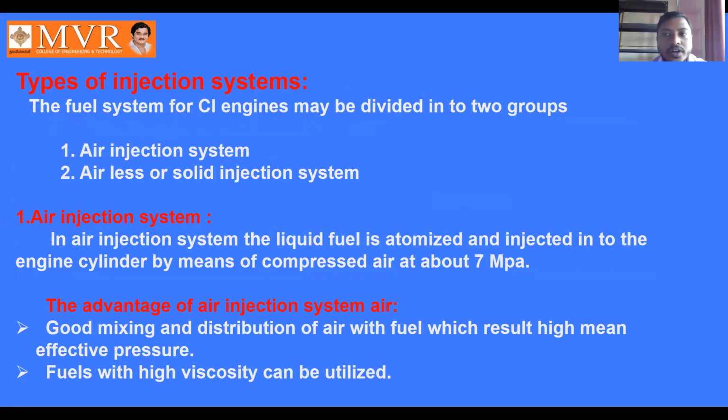See, we have different types of injection systems. The first is the air injection system, and the second is the airless or solid injection system. Coming to the air injection system, the liquid fuel is atomized, meaning converted into small particles, and injected into the engine cylinder by means of compressed air, at about 7